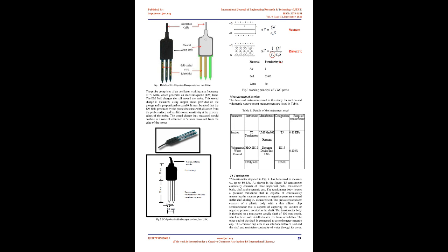2.1 Measurement of volumetric water content. It is found that volumetric water content is one of the most vital parameters for estimating the suction and in defining the WSR. Hence, it needs to be determined very precisely. In view of this, capacitance probes EC5 and ECTE, developed and supplied by Decagon Devices Incorporated, USA, that are capable of measuring it, are used in the present study.